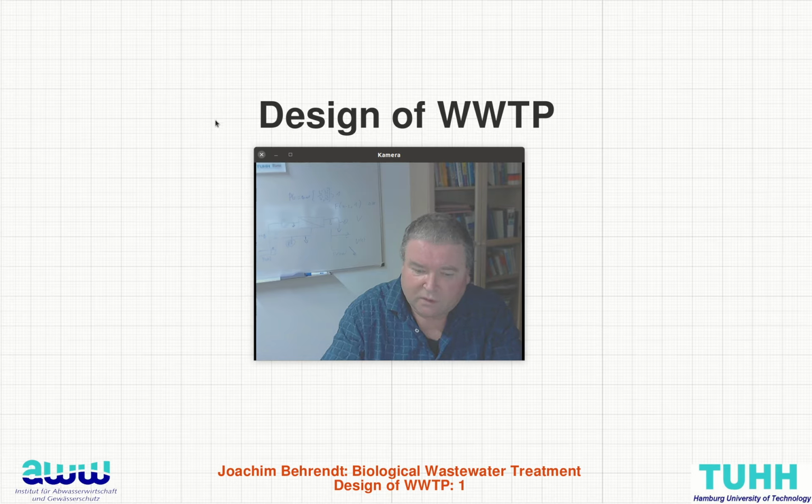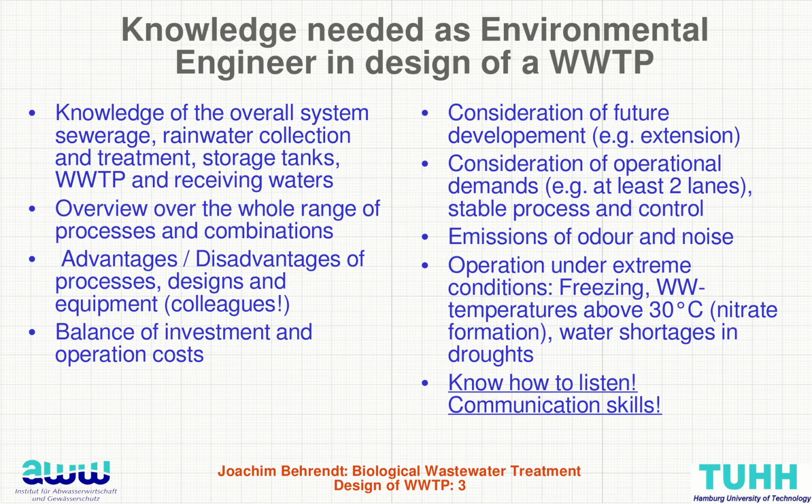Finally you also need to consider demands. You are always working in different lanes, at least 2 lanes in duplication. If you have to replace something or go into revision mode, then you don't have to switch off the whole wastewater treatment plant. Therefore normally you have different lanes, so that one or a few are always in operation.